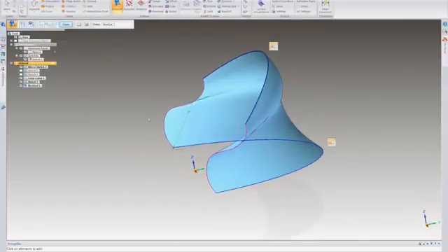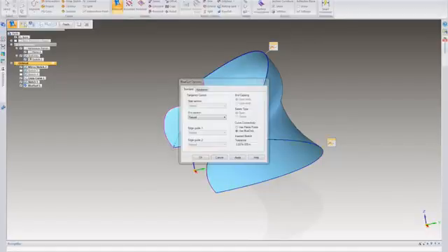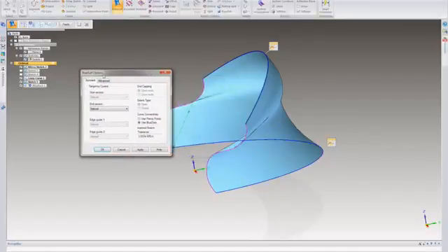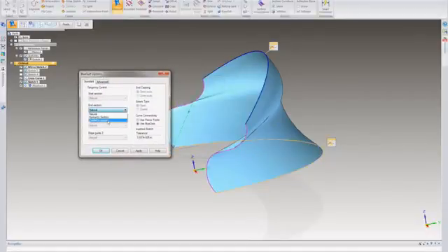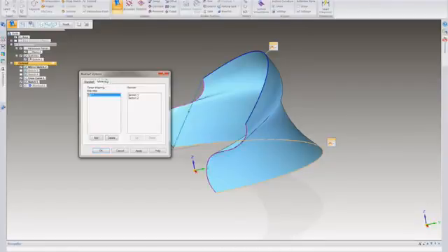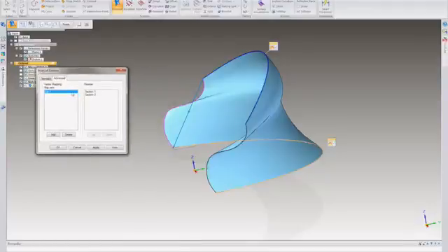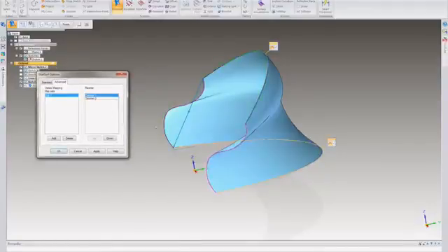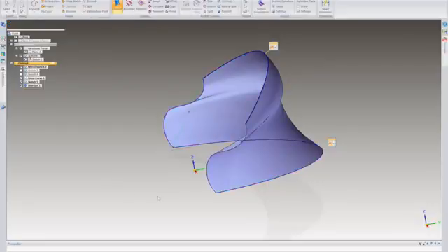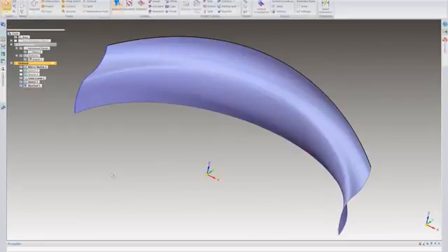All right, so at certain times under Blue Surf, you will get individual types of control points. So whether it's natural or normal dissection, parallel dissection, some other things that a lot of people don't really look at is the vertex mapping. All right, so if you can see, we actually have some points in space. If this was a square to a triangle, of course, sometimes the vertex don't map correctly. And I'll go ahead and quickly show you that on the next selection here as soon as I create it. All right, so that looks good right there.